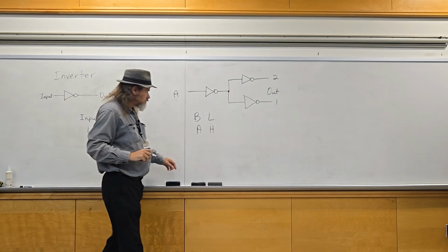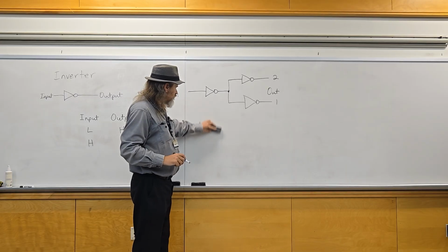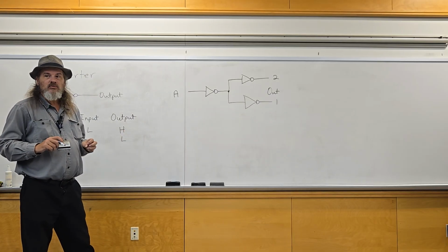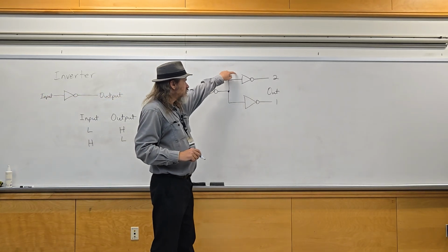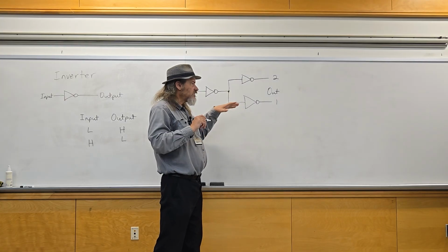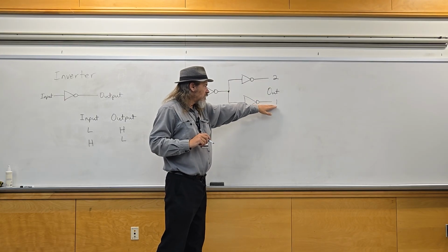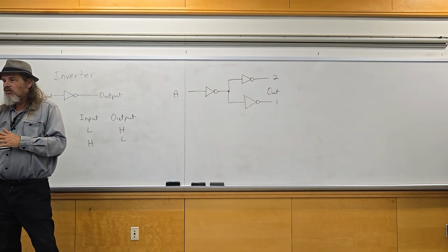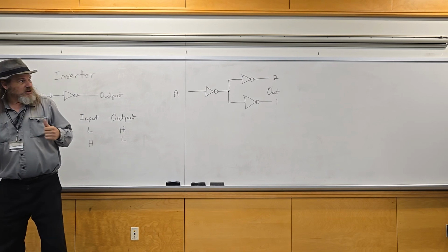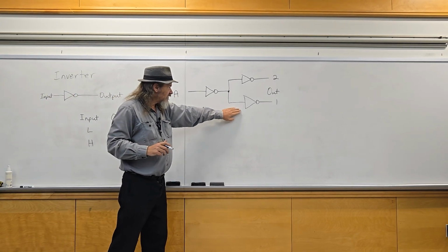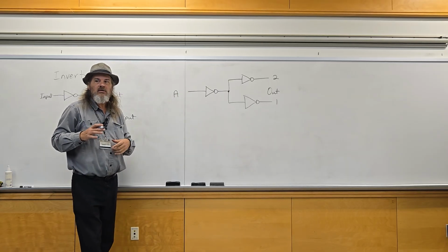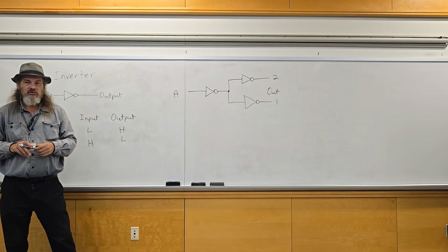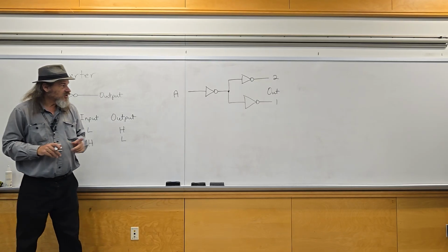The outputs would follow the input, but the power available would be higher because you have two gates driving the current for this. So if you would need to go to multiple gates from one output, you do a circuit like this, and it will generate enough power to drive the inputs of multiple gates. But this is okay.